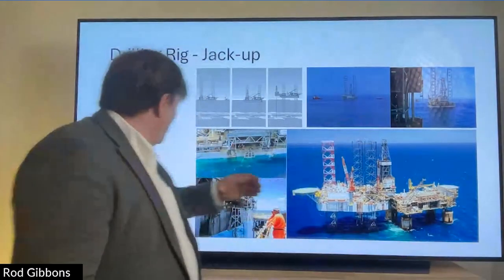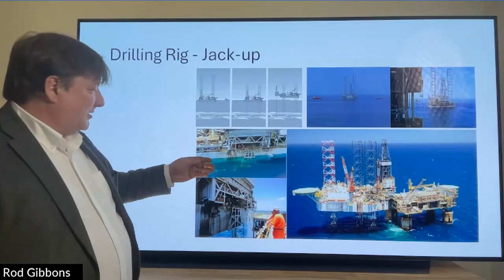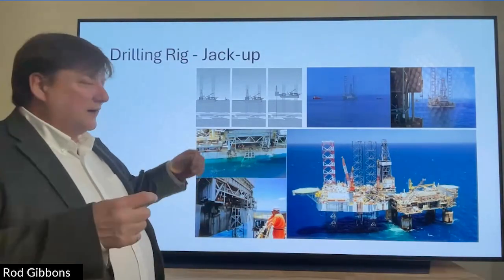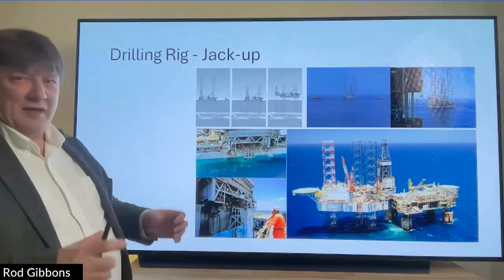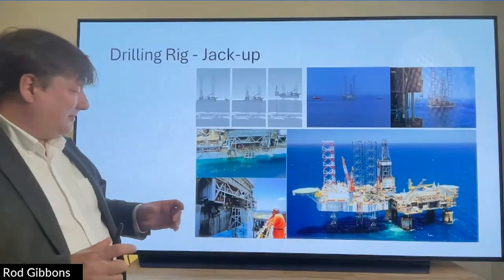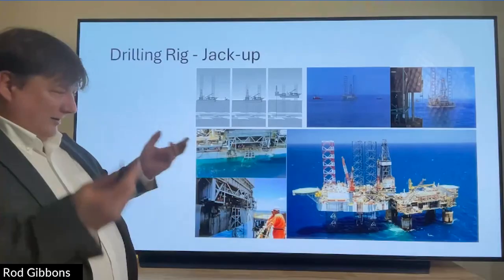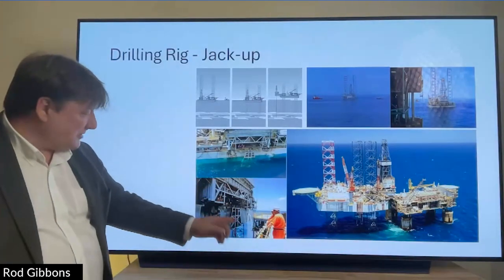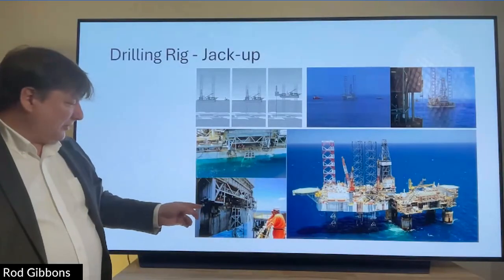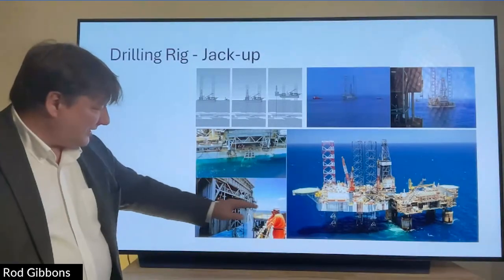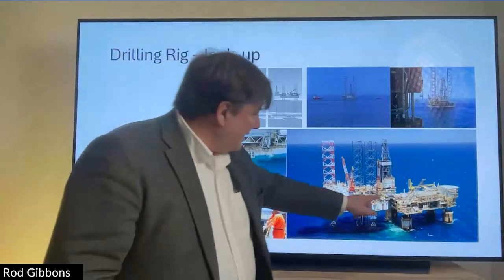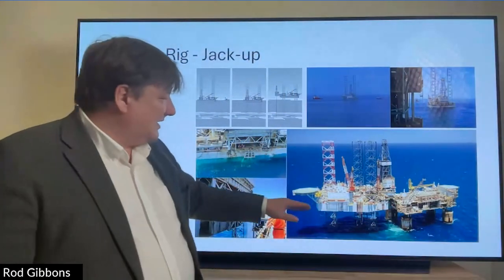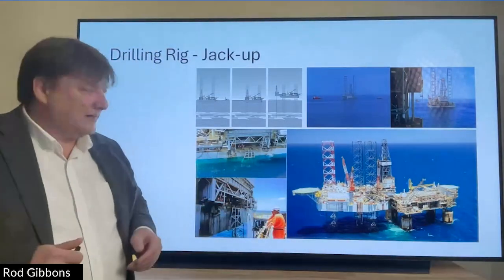So when it gets in close alongside the platform, it'll jack down its legs and then take on a bunch of water and preload to make sure that it doesn't punch through the seafloor. Then it'll get rid of the water and jack itself up. And so this picture is taken from the production platform, looking at the drilling rig, and it's going to skid out over this right here. And then it skids out over where the wells are to do the drilling. So that's a jackup drilling rig.